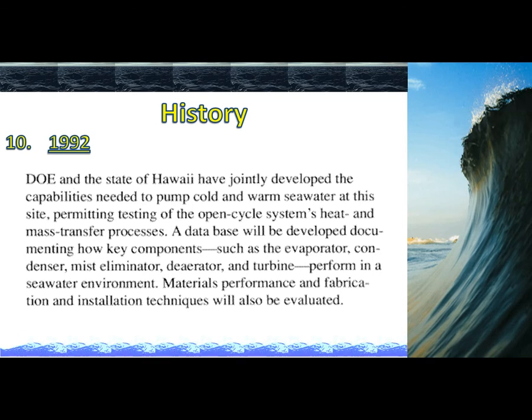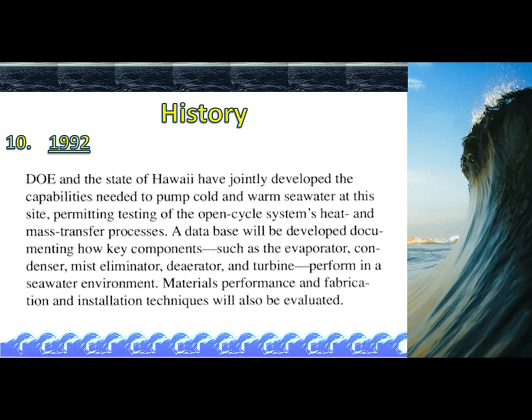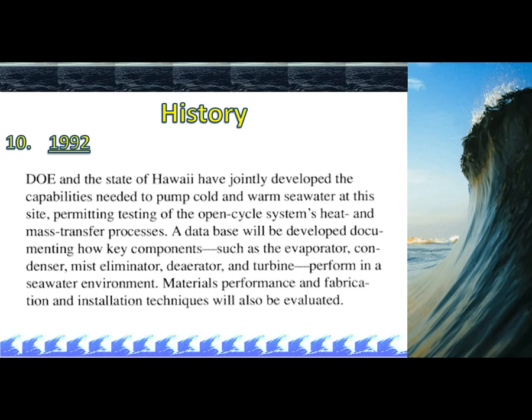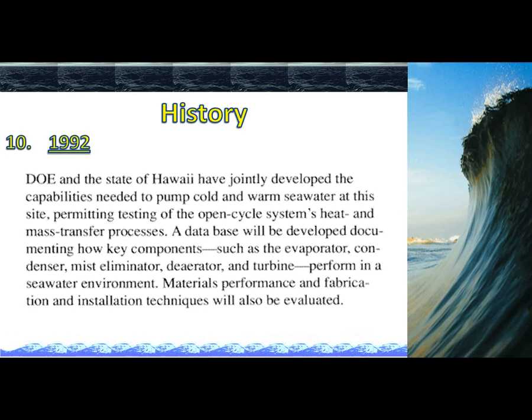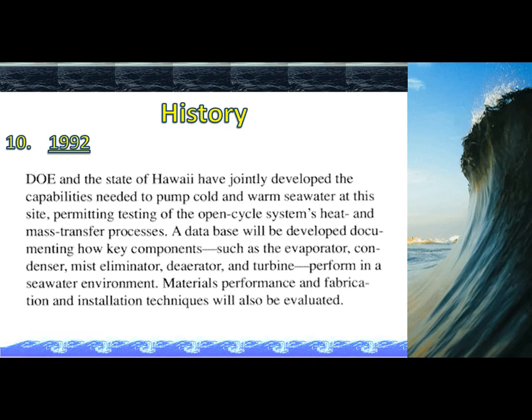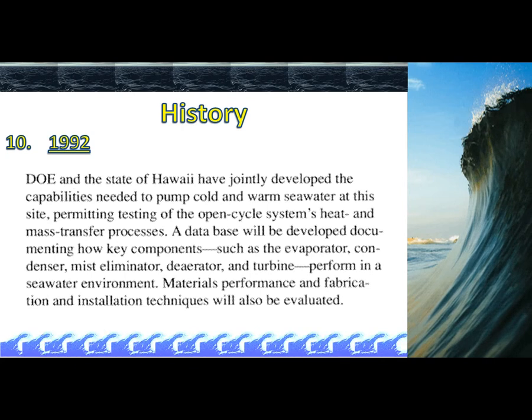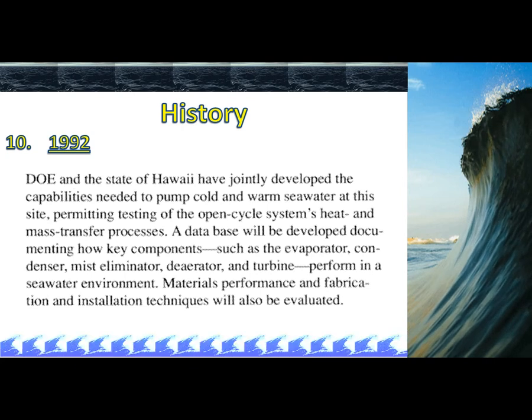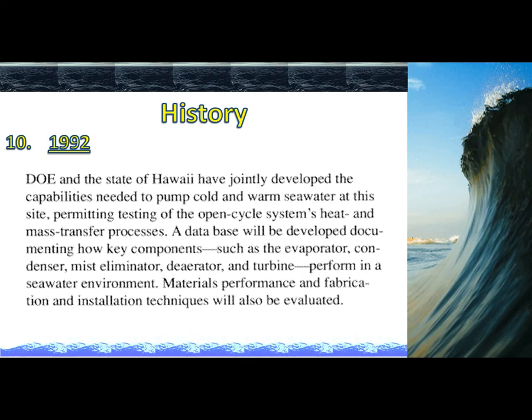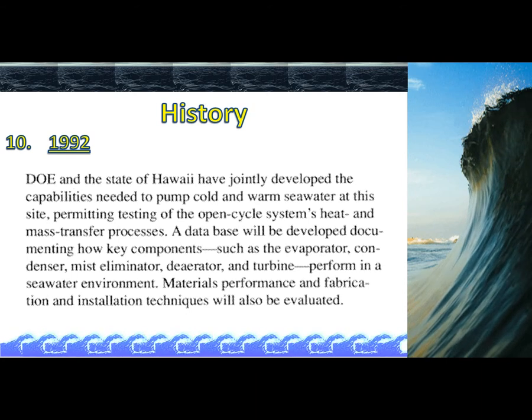DOE and the state of Hawaii have jointly developed the capabilities needed to pump cold and warm seawater at this site, permitting testing of the open cycle system's heat and mass transfer processes. A database will be developed documenting how key components, such as the evaporator, condenser, mist eliminator, deaerator, and turbine, perform in a seawater environment. Materials performance and fabrication and installation techniques will also be evaluated.